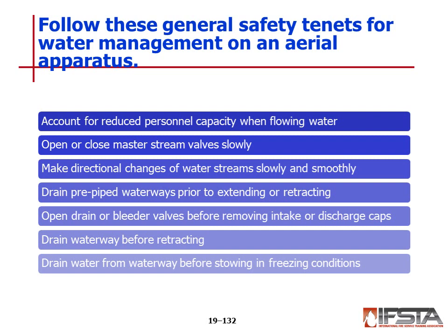Drain pre-piped waterways prior to extending or retracting. Open drain or bleeder valves before removing intake or discharge caps. Drain waterway before retracting. Drain water from waterway before stowing in freezing conditions.